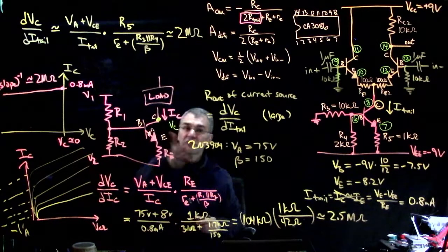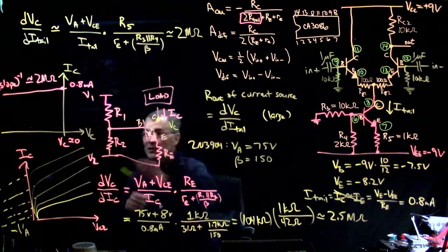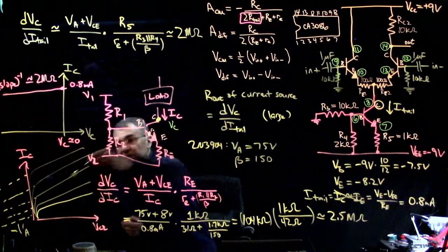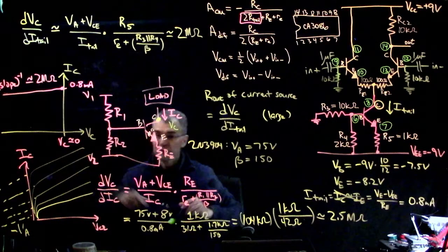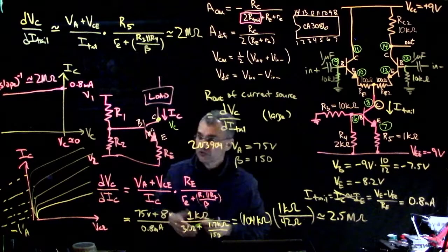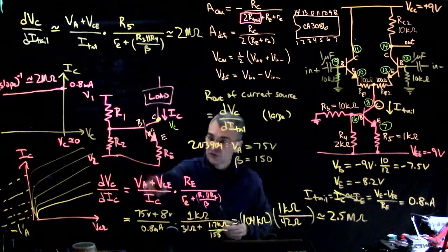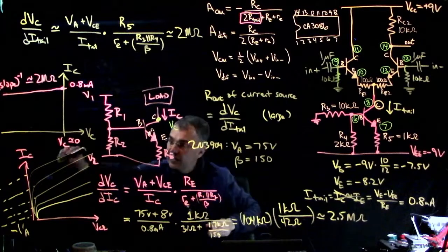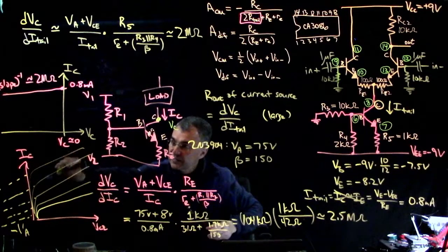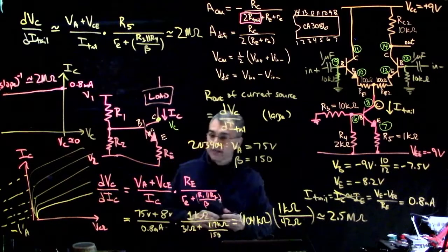So in the case of a 2N3904 transistor, if you extrapolate all of these slopes to where they would meet, it's at VCE equals minus 75 volts. Okay, so this is the Early voltage. So it's a transistor parameter. It parameterizes basically the slope of these curves.